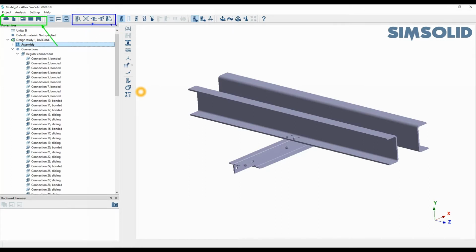Based upon the views that you have, obviously you can specify to fit everything to page. You can expand your window, you can zoom in, and you can also look at it from different perspectives, so from the XY plane, ZX plane, etc. Once you orientate your model in different views, you can actually save it so that it's always saved as a view in itself that you can refer back to.